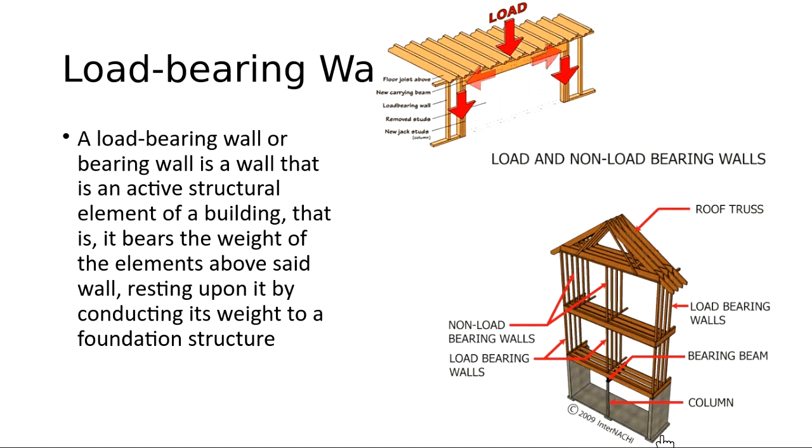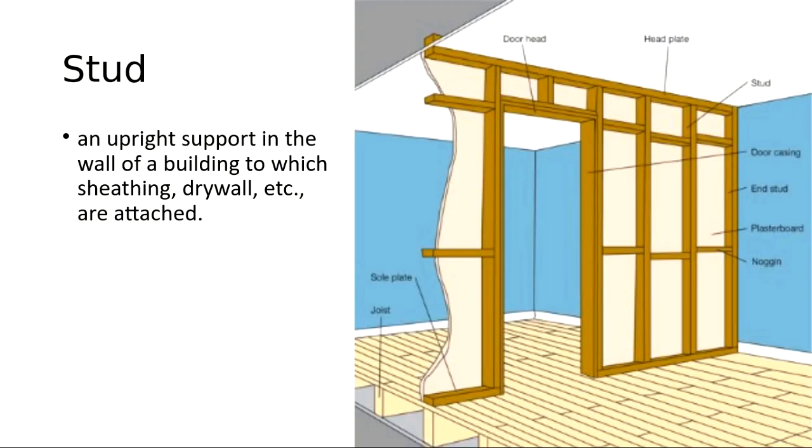This interior system of walls is transferring it down to a column that is holding up a beam underneath the center of the house, and there would be a footing under those columns. So you should look at your own house and figure out where the load-bearing walls are. And if you have a load-bearing wall, you have to be careful about opening it up. If you have a non-load-bearing wall, you can move things around very easily.